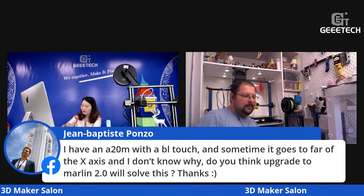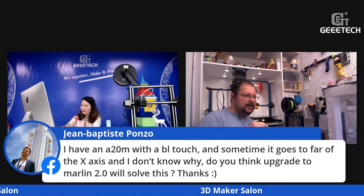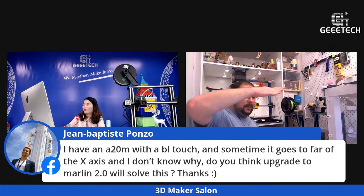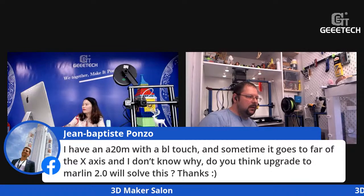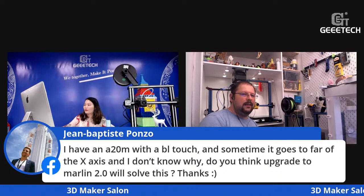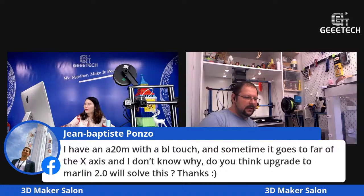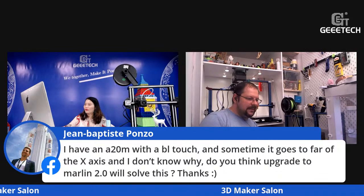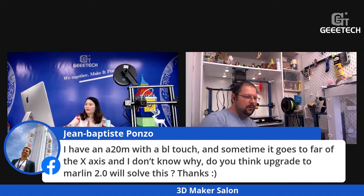it might introduce some little unexpected errors, exactly because the X-axis, or also the Y-axis, so not only the X-axis, maybe the X and Y-axis will be a little bit wavy. And I think if you upgrade the Marlin software, this won't change anything. Because as you see, on any of my printers, I tried BL Touch, I tried all of the auto bed leveling sensors, and I still level manually. Manually with a sheet of paper, in my opinion, is the best leveling method. You don't need automated things, because this can introduce exactly the problem you have.